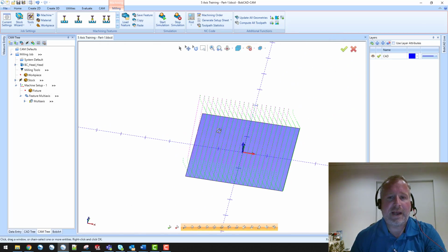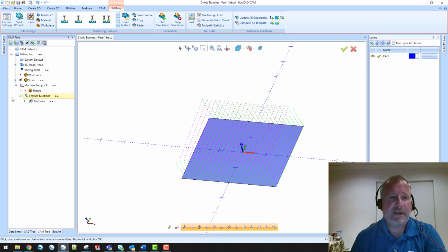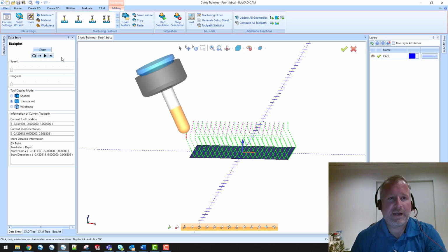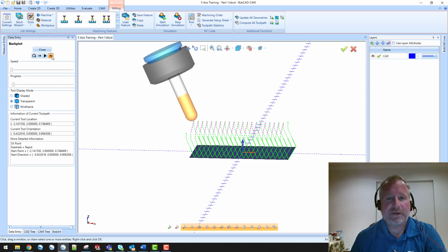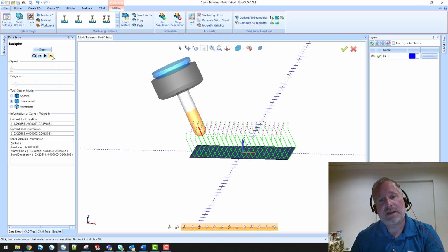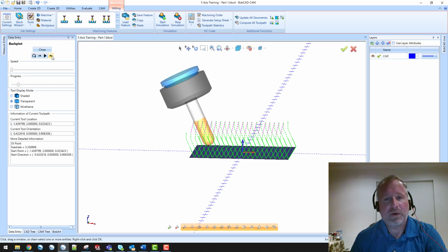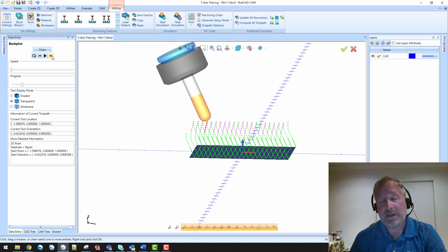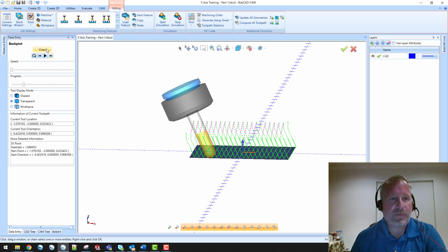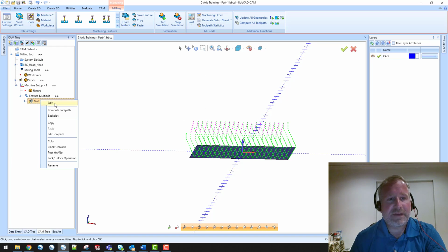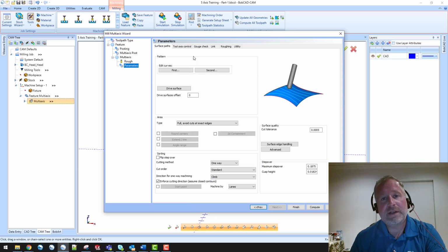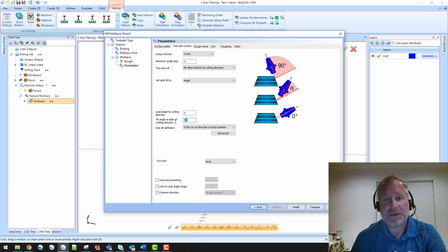And now looking at the cut, we can see that our tool is now tilted to the side relative to that cutting direction. And once again, as we spoke before, this is applied to all of the passes in this operation. So if we set that option to a negative value, we can tilt that tool to the other side.